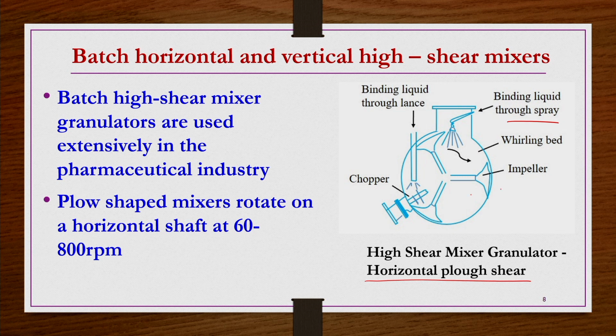Right. So inside this equipment there is an impeller, and that impeller rotates, because it has a rotational provision inside. We are showing only a frontal view here. When it rotates, whatever feed you have taken along with the binding liquid undergoes continuous mixing under high shear, okay. Because of that high shear mixing, the granulation takes place. So here also the process seems to be very simple. Of course, with this equipment we are not getting into the design concept.